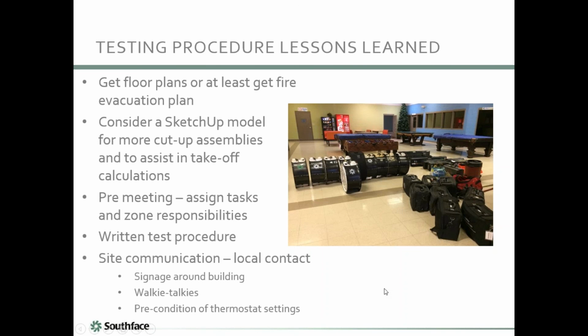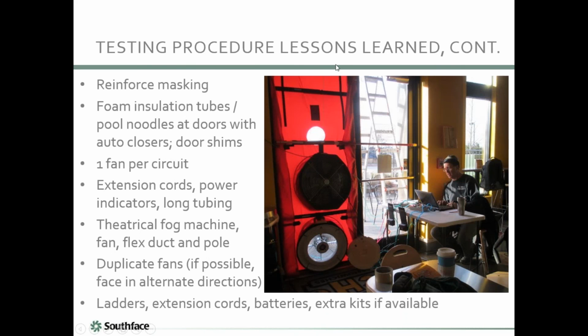Well, we could have a webinar about the challenges of masking up vents on commercial buildings. It's true, but you're going to have bigger vents. You're likely going to have outside air on these commercial buildings. You very possibly are going to have large exhaust fans. So you need to make an assessment of what needs to be taped off when doing a depressurization test. If I'm doing a pressurization test, there's different stuff that needs to be taped off based on how dampers would operate. So make sure you identify those things, and then have the tools in place to actually do that.